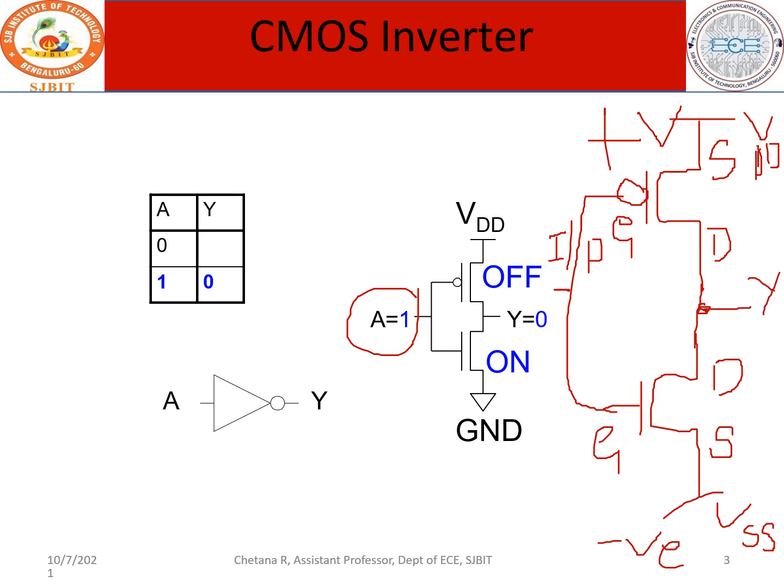So please remember, in CMOS structure, always the output is taken at the drain junction. So this is how you have to remember the construction of a CMOS inverter. Now let us justify whether this truth table works or not. Alright, when A is equal to 1. If this is okay, we'll go on with the next skeletal structure. Let me show how the CMOS inverter works in my next slide. I'll go to the next slide.